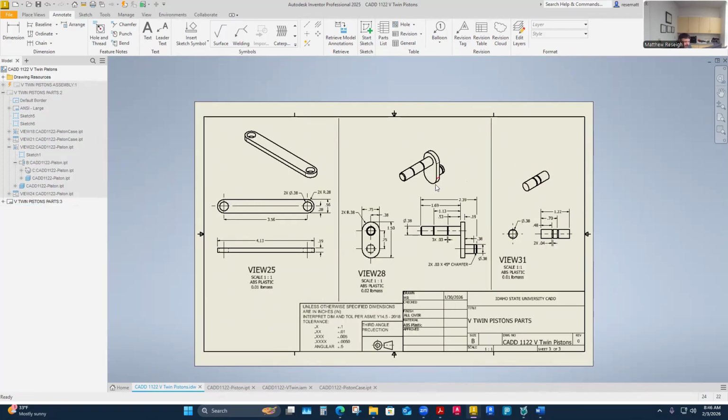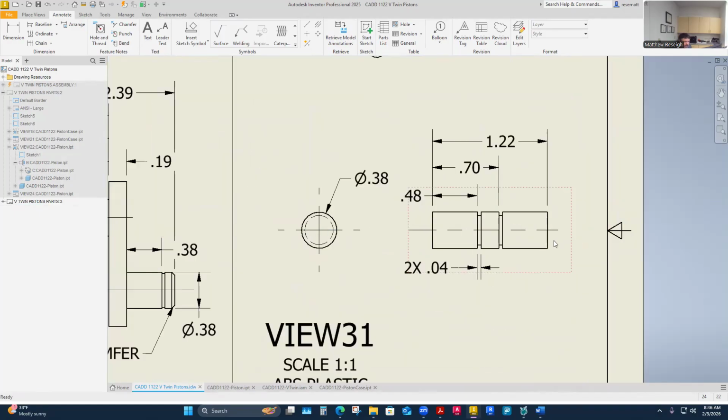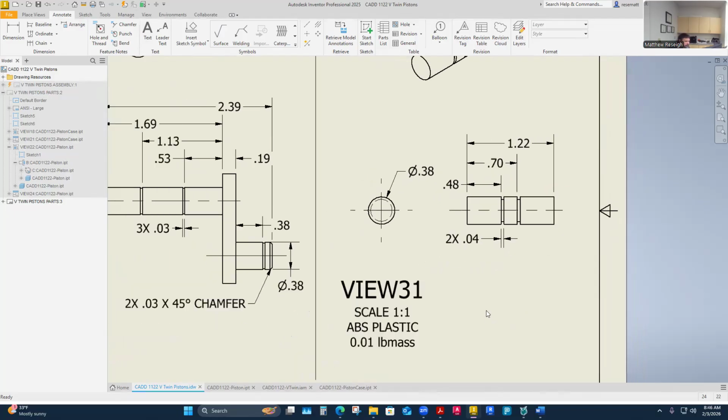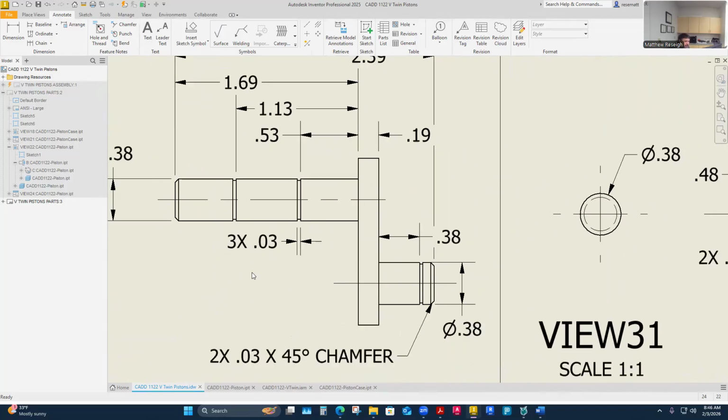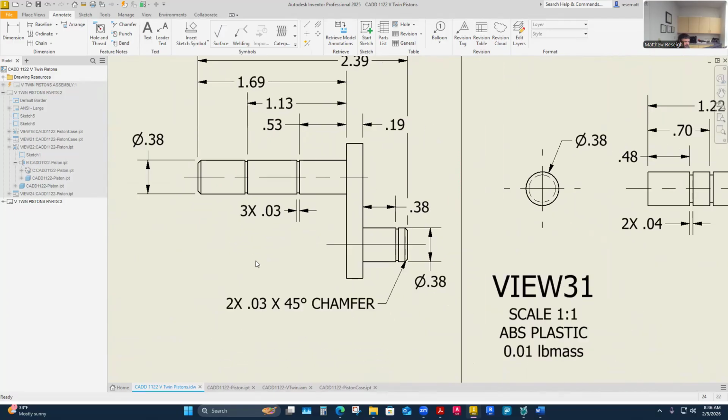Nothing really with the wrist pin and that. Those are good. I changed mine to accept the easier-to-apply retainer, and that worked great. It's not the snap ring there, but it kind of functions like a snap ring. It's the one you just slap on there, and you can insert it from the end of the piston. It was way easier to assemble. That was a good change. Of course, the grooves on those are different than the grooves for these ones here, right? That was me following the documentation that I pulled off from McMaster-Carr. It gave me a groove width and a groove diameter, and that's how I modeled mine.